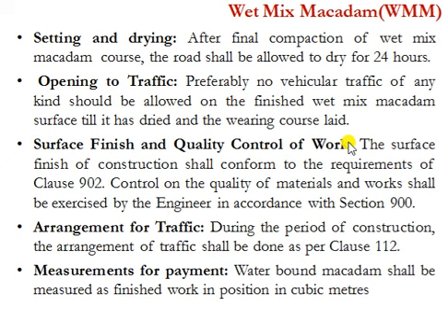And here the control of quality of materials should be in accordance with section 900 or table 400 of IRC. For example, the gradation should conform to IS 2386 part 1. So the material gradation should be as specified in IS 2386 part 1.